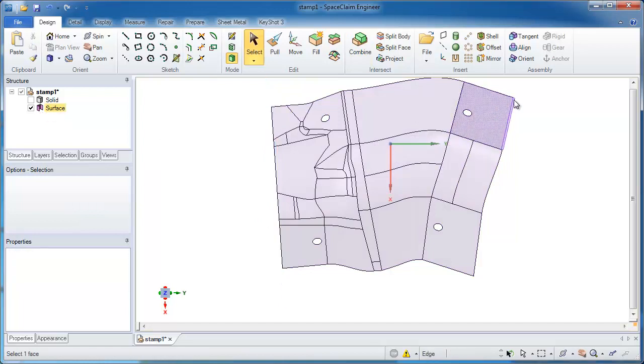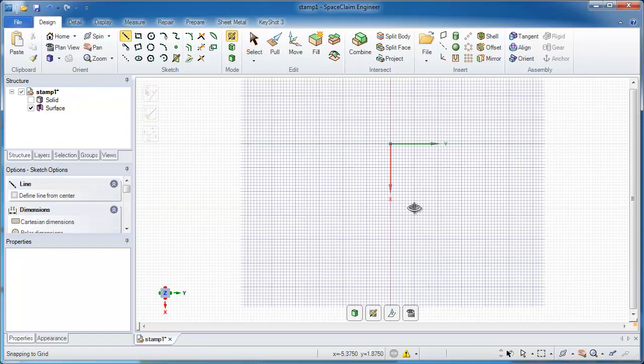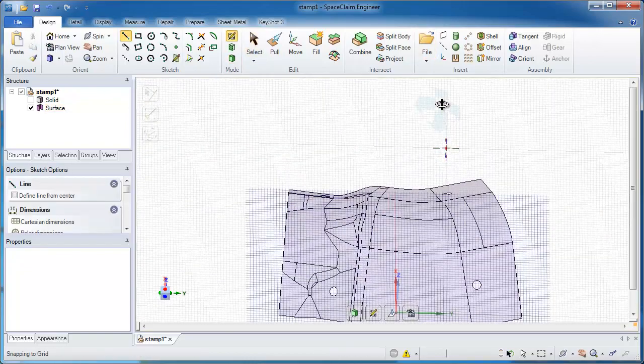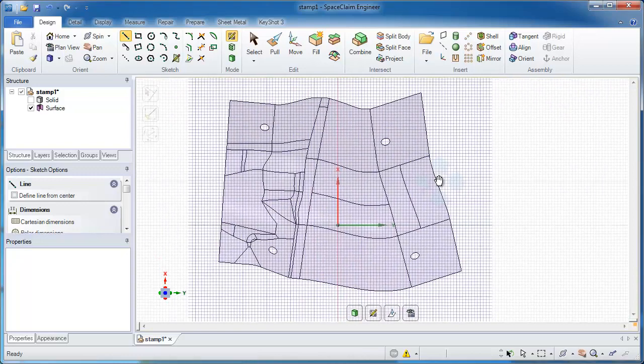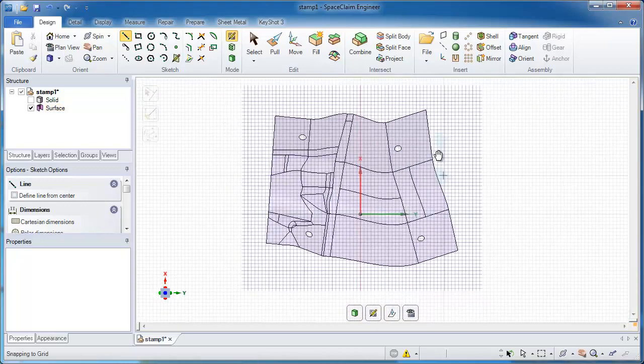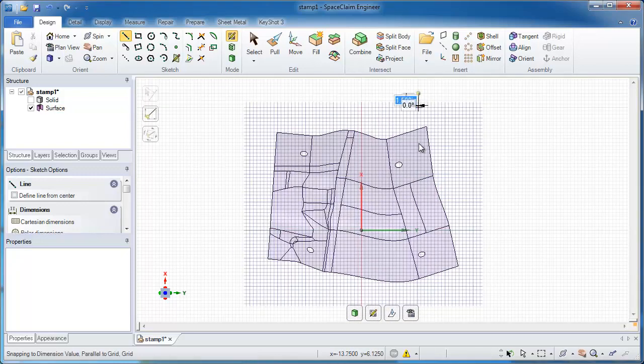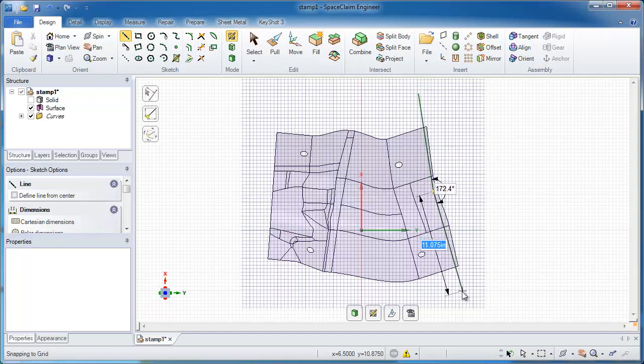Now, as for the contour on the right-hand side, I may elect to use something of a curve instead of a planar surface for trimming that back and making it look a little more clean. So I'm going to the bottom side. I'm looking at this from the bottom view. And when I say curves, I really meant just maybe a couple of lines that I could draw in. Just lines that are a couple degrees apart, so they look like roughly 8 degrees apart.